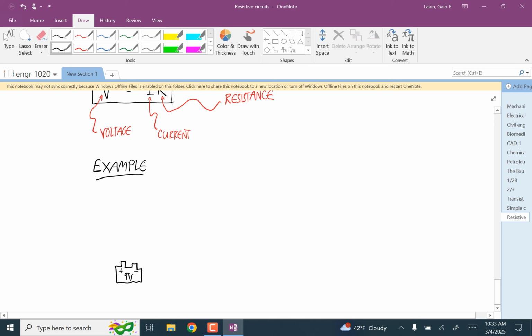What that 9-volt battery means is that the positive side electric potential is 9 volts higher than the lower side. It could be an electric potential of 1,000,009 volts and then an electric potential of 1,000,000 volts. All that matters is the difference between them for pushing current through a circuit.